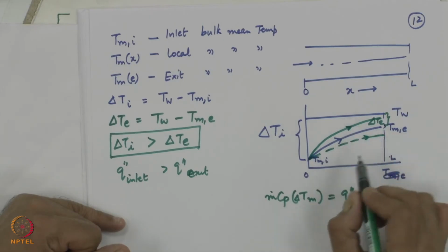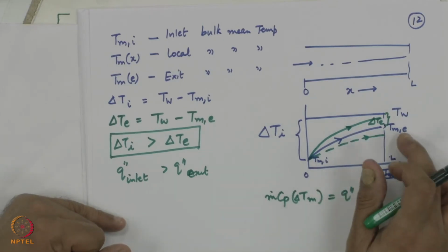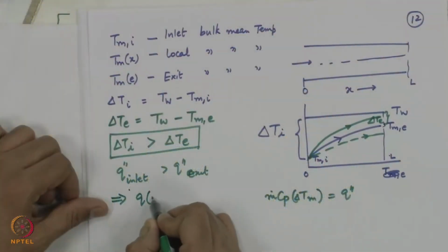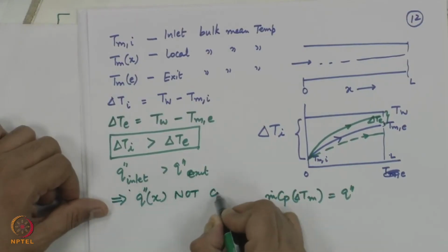All I am trying to say is, smaller mass flow rate, the temperature rise would be higher. Larger the mass flow rate of the colder fluid, temperature rise would be smaller. So, the nature of the curve, the shape, etc., would be identical. The slope of the curve would change because of the mass flow rate. So, Q at every location is not a constant, it is varying.